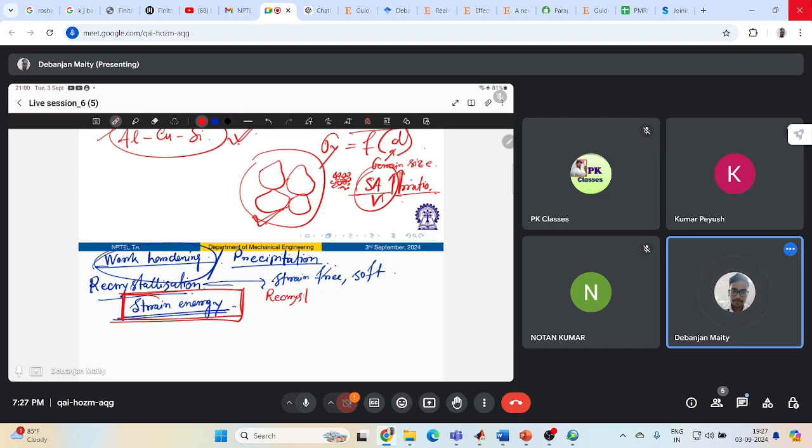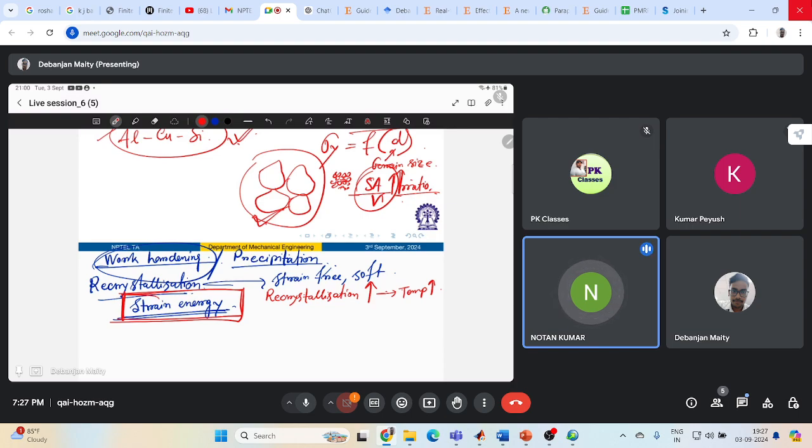Yes, sir. The extent of recrystallization increases with temperature and time. Right. So it is expected that the strength or hardness of your work hardened material will tend to decrease with increase in temperature and time, as you suggested.